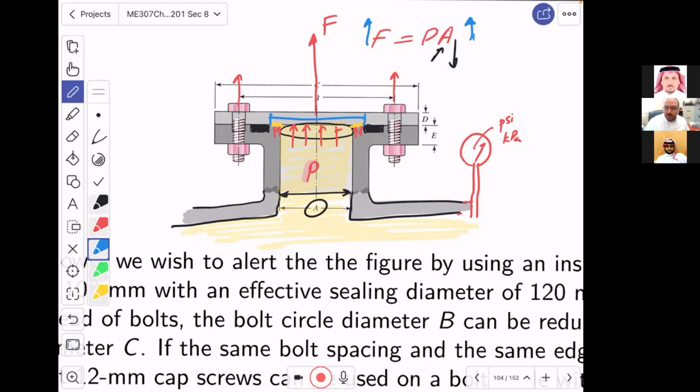If you said, let me use this area as an approximation, you are on the risky side, not on the safe side. If you want to be on the safe side and calculate the stresses with your mobile phone, you should probably, as a rough estimation, be better off using B as a distance rather than A. Here, you become conservative. You are putting a much larger area and the force will be much larger, but it will make you safe. However, calculating a smaller area is very risky. So you need to be very careful.